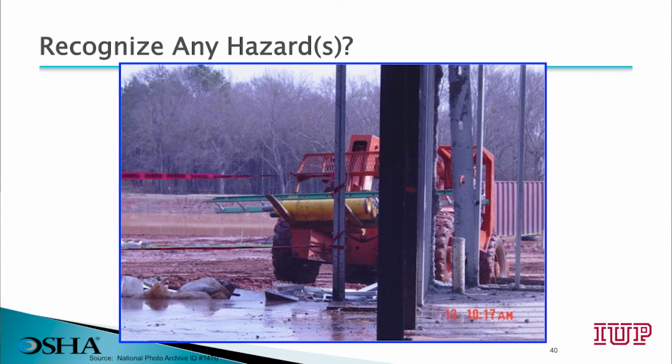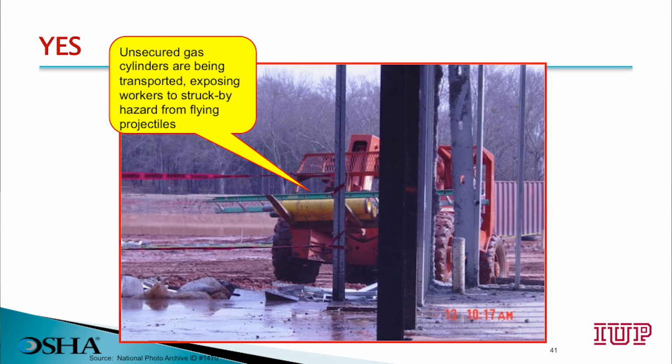How about this job site? Do you recognize any hazards here? Unsecured gas cylinders are being transported, exposing workers to struck by hazards from flying projectiles.